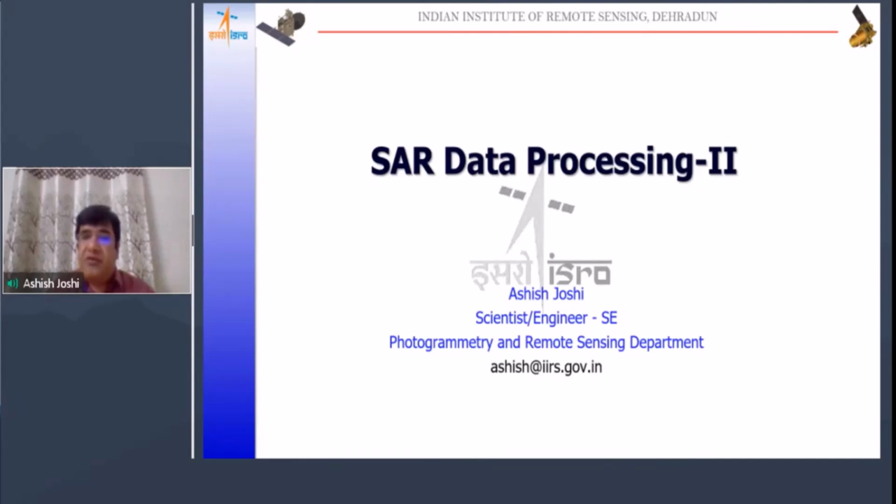In the last webinar, we have seen the SAR data processing in which we have seen the algorithms of SAR raw data processing. In that webinar, we have seen how the raw data is converted to the processed data using the signal processing algorithms. We saw the concepts of the pulse compression techniques and synthetic array approach. From those algorithms, we converted the raw data to the processed data using the range Doppler algorithm, which mainly uses the range compression, azimuth compression, and the range cell migration correction algorithms.